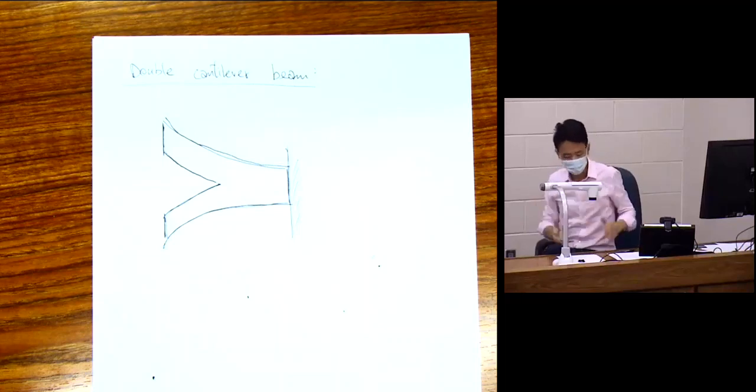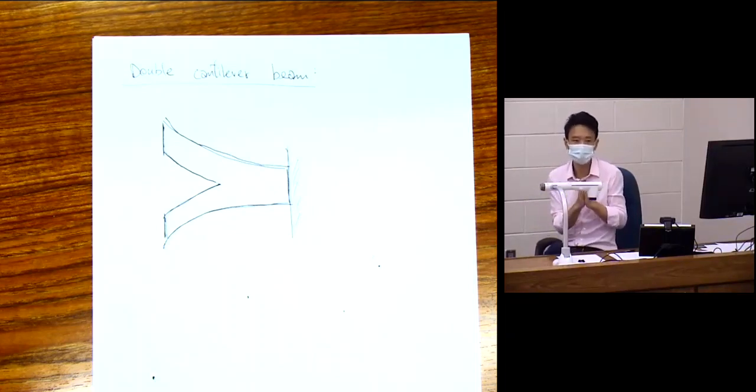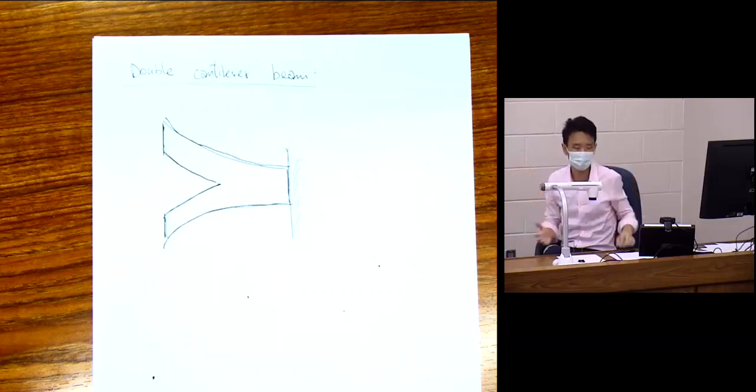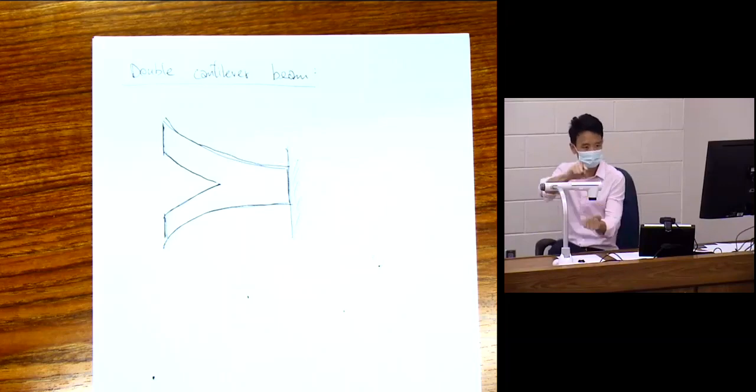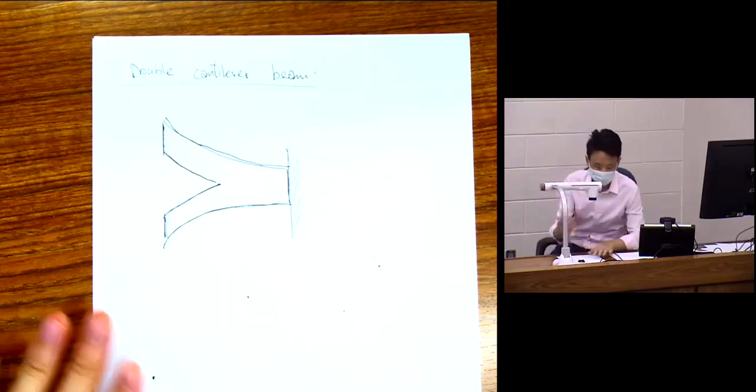You have two plates that are glued together. Now you want to peel it off, right? That's a crack problem, right? I mean, you typically use it in a reverse manner, because you want to glue strong enough that it does not allow you to fracture the two slabs of whatever material you had, right? So this is a double cantilever beam configuration, right? The stress situation is exactly the same.